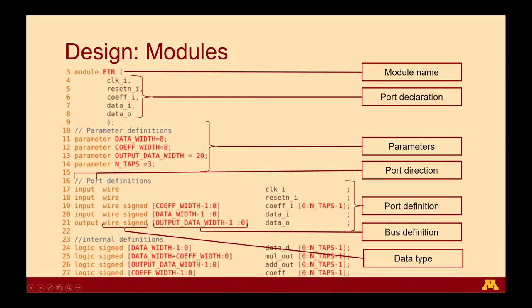And lastly, we define any internal signals which we need to use. It's generally good practice to define any signals used, like how in C, if you want to use integers or doubles, you define the internal variables as int or double. The reason is that if you do not define these quantities, by default Verilog takes them as a wire type, which is a single bit type. And if you intended it to be a bus type of data, you will run into a lot of issues when you're designing, but you'll never know why this happened.